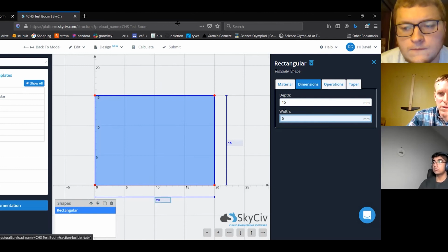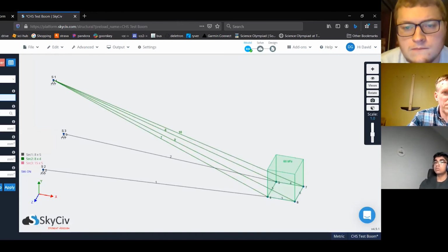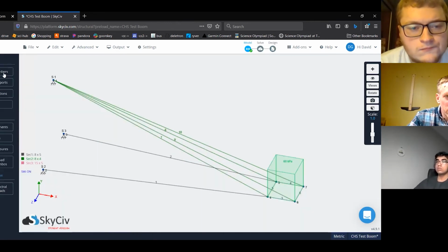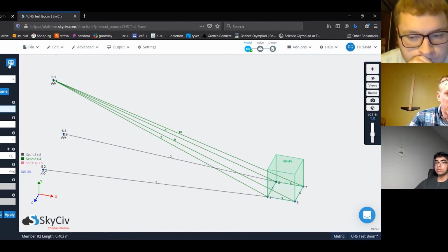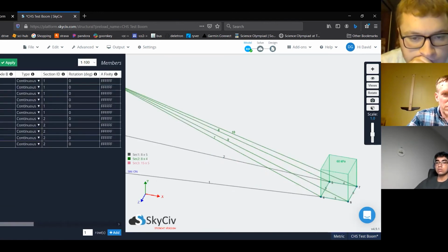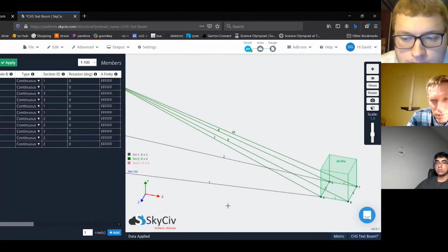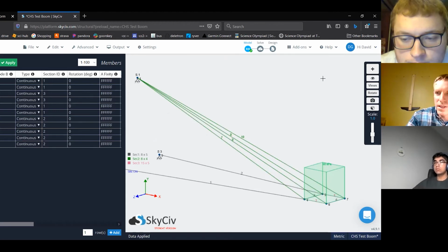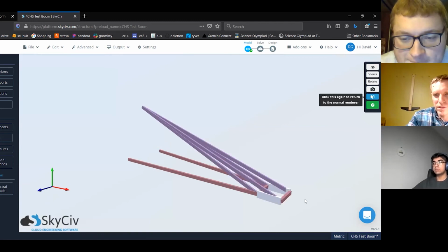So then you submit, oh, wait, I don't think I did that right. No, I think it's right. Yeah, 15 by 5. Okay, so then we want to make sure that, oh no, we go back to members, and we have to change 3 and 4 to be this section 3, which is 15 by 5 now. So we go to spreadsheet, go to members 3 and 4, make those section ID number 3, and we apply that, and they show up kind of pinkish, and we can see the 3D view of that, and yes, they're much taller than the other ones.